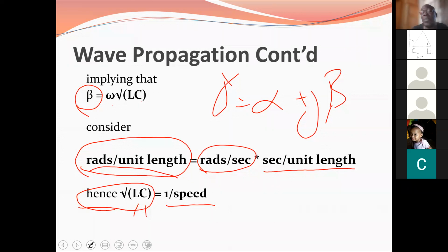All right, so I'm saying all of that to say that your system, if we do not take transients into consideration, may result in over voltages, which then produces the flashovers that we mentioned, because the voltage back on the system, from the line back on the system, would be higher than what you would have set up your system for. All right? Okay?